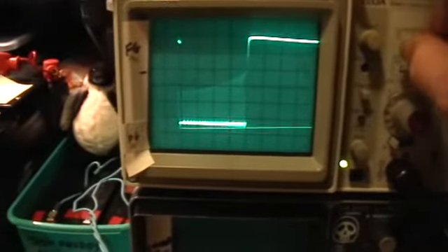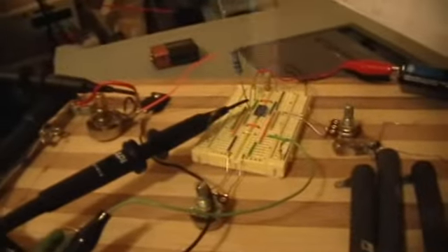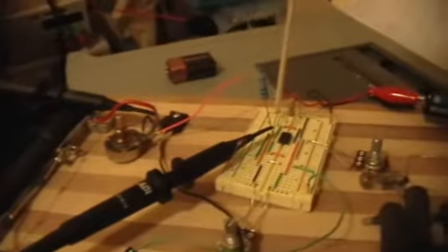Can you see that? See all that nice regular oscillation there where the MOSFET is not switching cleanly? That's coming, or rather the 555 timer is not switching cleanly. All of that is coming from the 555 timer, and that's what's inducing those oscillations in the MOSFET. The timer is not even connected to the Ainslie circuit right now, except through its ground lead, which is irrelevant, except for grounding the scope, of course.